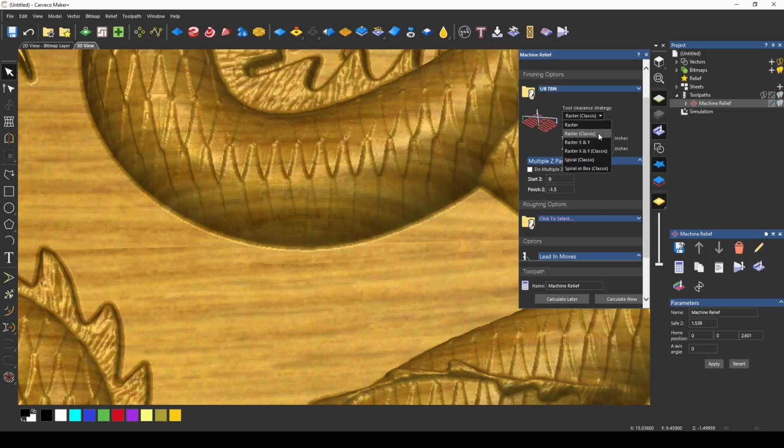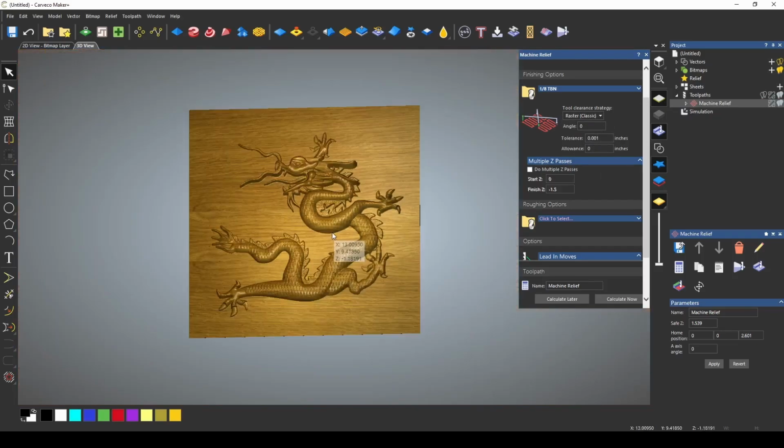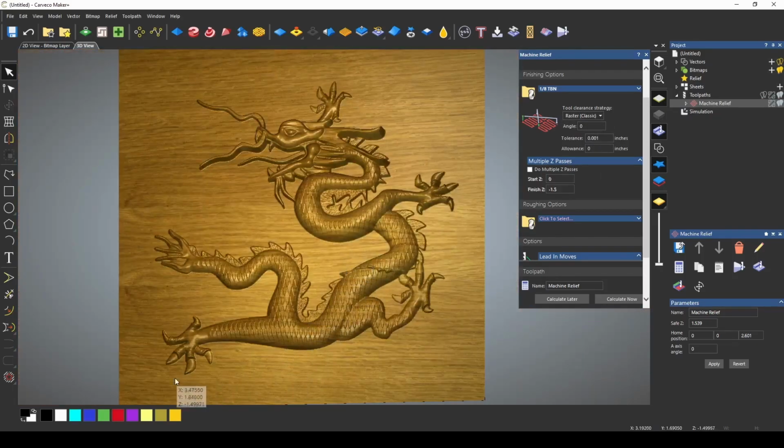Okay, going back up to our toolpath strategies, our Raster toolpath, because the Raster toolpath goes from left to right, back and forth, a lot of times you're following the grain of the wood. You're either following with the grain of the wood, or you may have your board turned with the grain north and south, and so you may be running against the grain of the wood. You can change your angle to run at a 20 to 45 degree, and this will change the Raster direction to run diagonally across your material. That can help with not running with or against the grain of the wood.